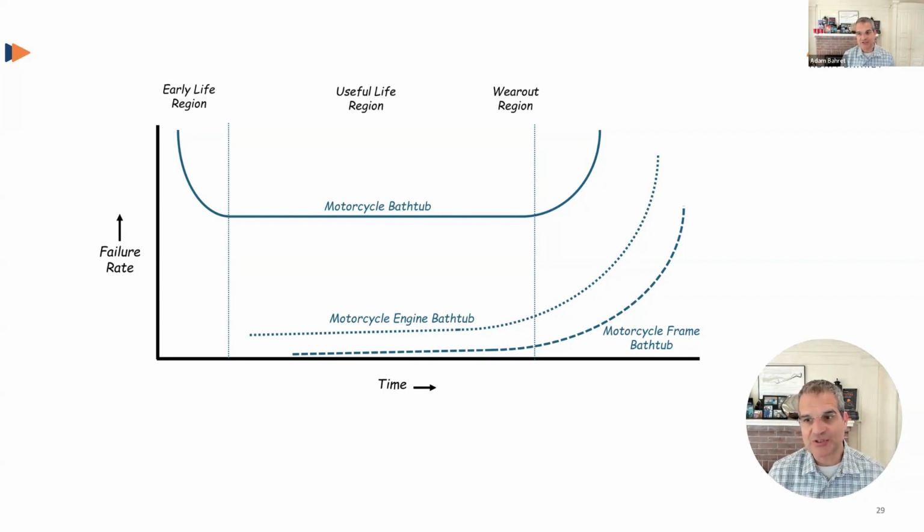So it can change. That's why it's part of when you design the product, the market it's going into, and your objectives. You want to have the wear out be the right time to wear out, not too long, not too short, because it does come at a cost. This is why accelerated life testing is so critical to validate that you are hitting that target and allowing you to balance it by either making it last longer if needed or allow it to have a shorter life, which provides benefit for either cost point or technology development.